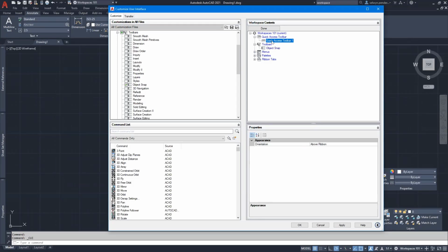Another one that's in here is the Quick Access Toolbar. The Quick Access Toolbar is based on this entry here. What I would suggest is removing that entry and using this entry down here, partial customization files, custom, quick access toolbars, and enter that one for the quick access toolbar. So when you modify or when you update your AutoCAD, if it's saved in the custom menu, if you're not sure where the custom menu is kept, I'll show you in just a moment.